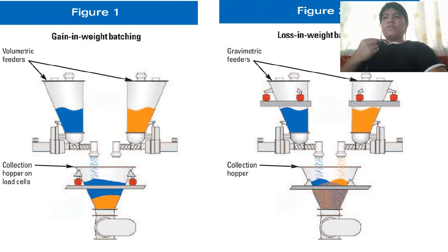To set the rate in a volumetric feeder, the user turns on the feeder auger and begins catching. A volumetric feeder uses a catching sample method, so it samples in a container for a time period.